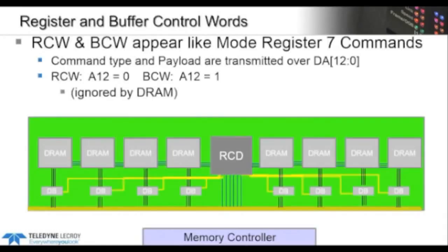Okay, if you're going to be involved with testing and qualifying LRDIMMs, it's really helpful to understand the structure and flow of these commands. This is some of the stuff that Doug talked about, but it bears repeating. Again, standard commands, your write, your refresh, your MRS, are going to flow through the register to the DRAM.